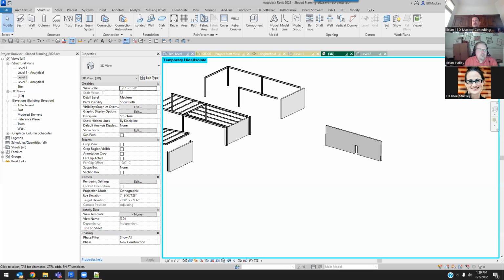So when you go to PDF, first off, I'm assuming, Jason, you printed using multiple PDF printers, the out of the box, if you're in 23, PDF exporter, or like Qt PDF, not just Bluebeam or Adobe. Most of the time I find issues with printing to PDF, it's Bluebeam or Adobe. And honest truth, there's a free one out there called Qt PDF. I use that one all the time and I have the most success with it.